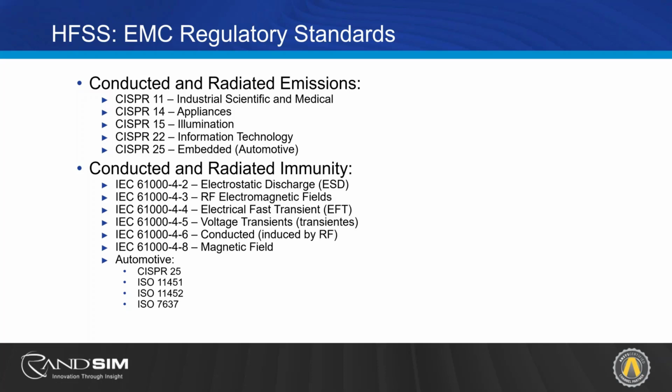A couple of things that I didn't show here, but that are examples within HFSS that you could just open up and use as a starting point, are electrostatic discharge, as well as voltage transients or electromagnetic pulses. So those are other things that you could simulate and evaluate within the HFSS tool so that you at least have an idea of how well it will perform prior to fabrication of your circuit boards.